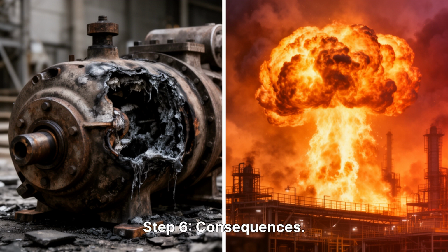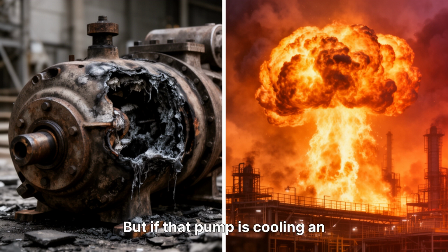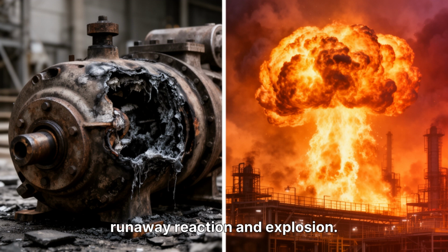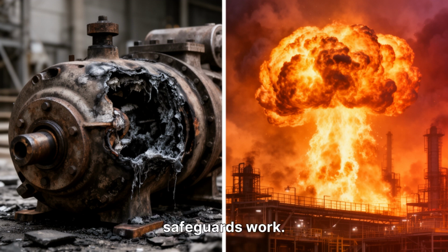Step 6, consequences. If no flow happens, what is the result? The pump might run dry and overheat. That's equipment damage. But if that pump is cooling an exothermic reactor, no flow could mean a runaway reaction and explosion. We always evaluate the consequence assuming no safeguards work.